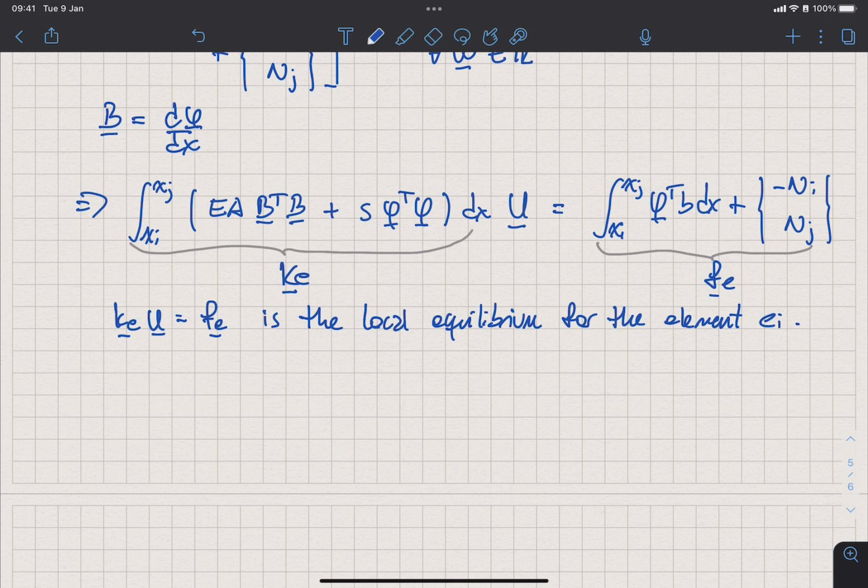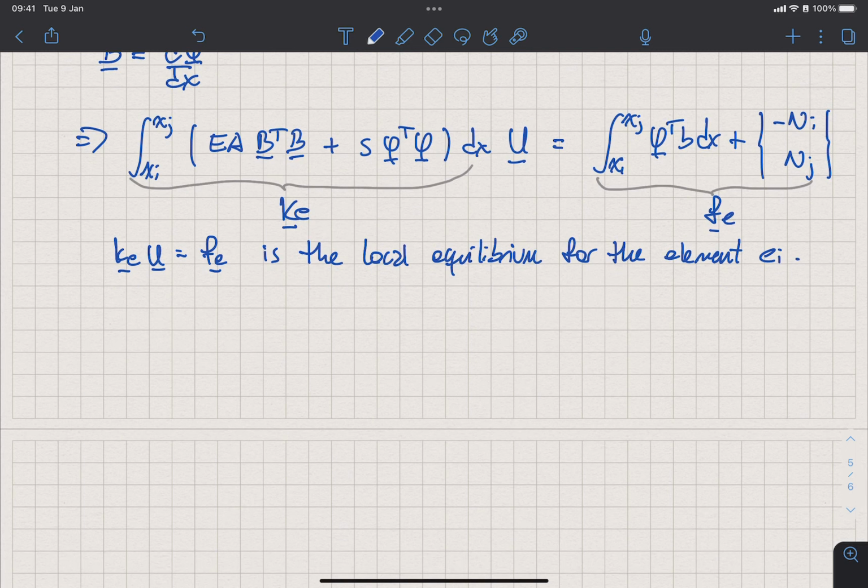So in essence, we take one element, and then we obtain the contribution of the neighboring element, and then the next neighboring element, and you see that all these forces that are shared between elements are going to cancel out one another, right? And so the only forces that are going to be left without canceling are the ones at the boundary. And these are your boundary conditions for the whole bar. Let's write that down, and then we're going to take a break.